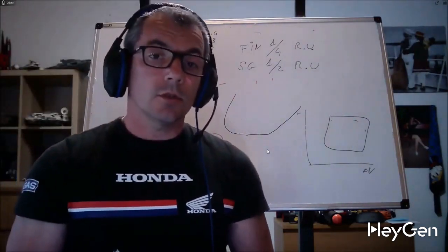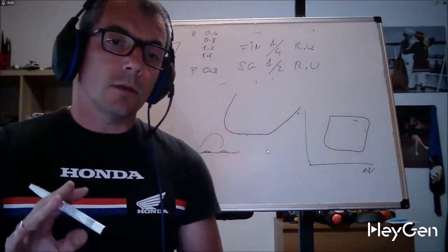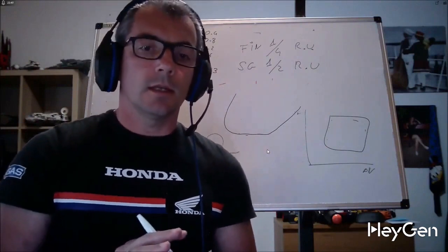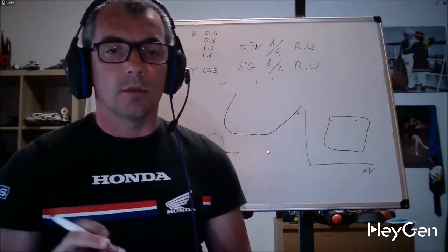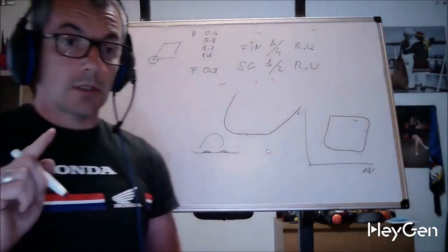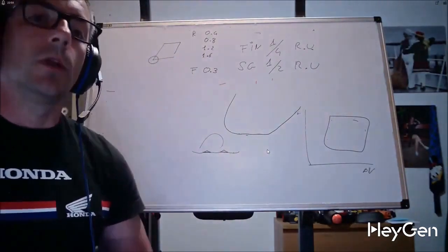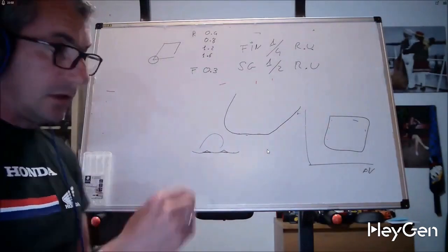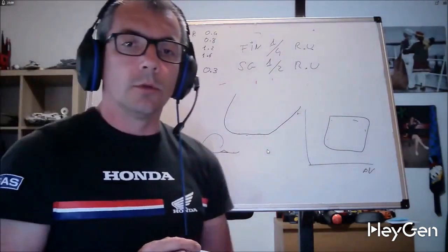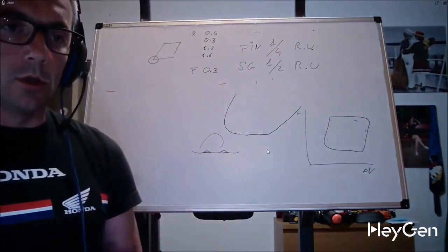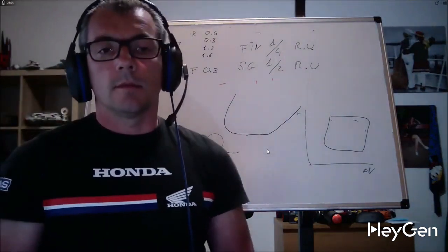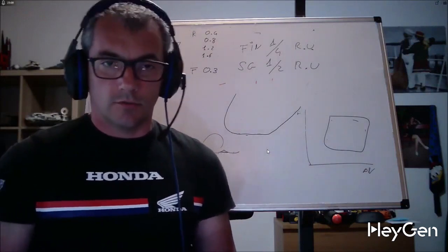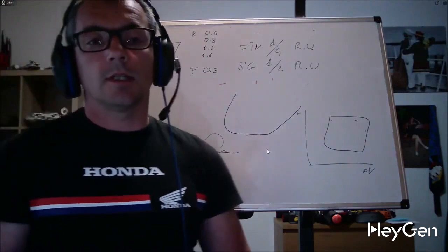In finishing, it may seem absurd, but we must never exaggerate with the radii of the tools, because then we won't have good tolerance. To maintain tolerances, two things are important, if possible, and if it's worth it. A positive insert. So, the second line of what we wrote after, a tool radius that is not too large. Unless we are doing particular machining, abundant cooling of the part is necessary because of thermal expansion.